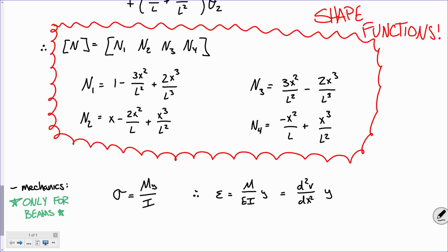Remember the Euler-Bernoulli beam bending expression? That's how you do double integration. That's the first beam bending formula that you learn. You take your moment function, integrate it twice, apply boundary conditions, and then you get your beam deflection. I know you've done it before. It might have been a while, but I know you have. All right? So, is that a fair statement?